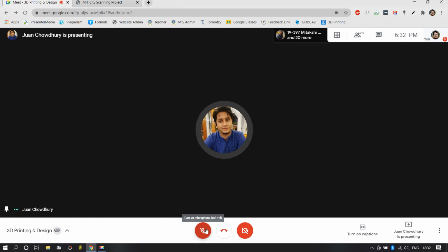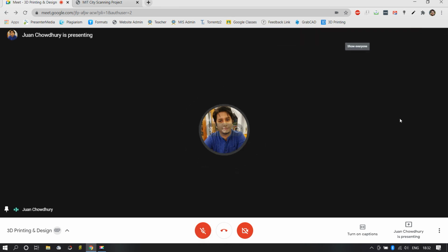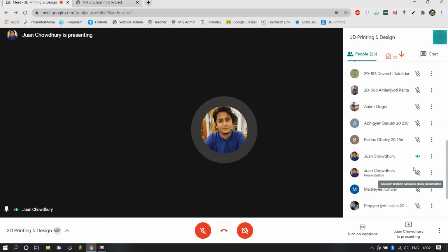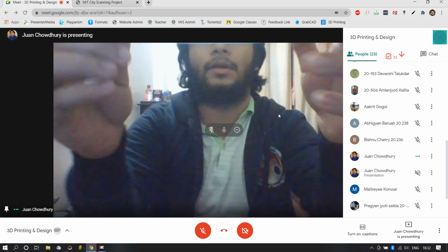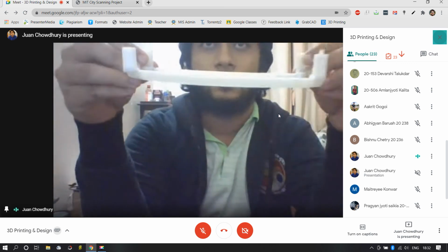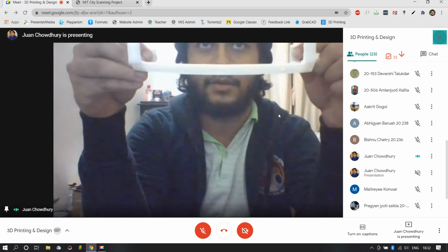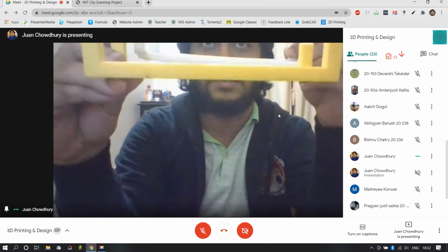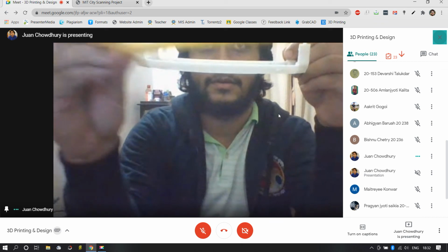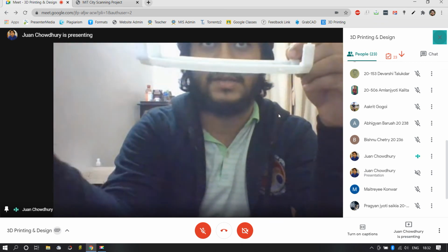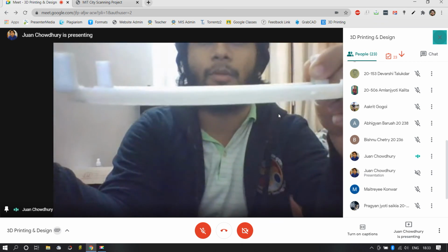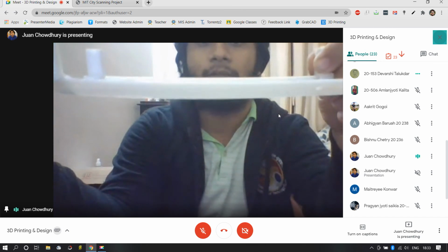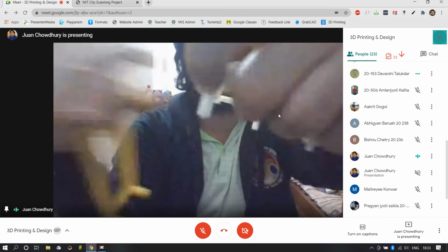Now, if you remember, I was talking about the heating problem, the thermal warpage. So we printed another one without a table that had heat. Can you see the bend of the material now? It is not straight like this. This is very straight, but this is not. I hope you can appreciate the problem. Can you see the curvature? This is a thermal warpage problem. This part is now redundant.